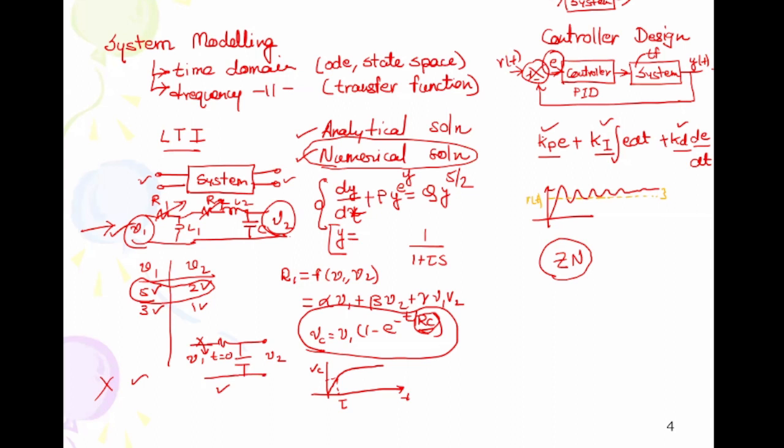Now you have to apply optimization. When you apply optimization, first of all, somewhere you have to write what your objective is and what you basically want to come out with by using optimization. What is your aim? There is a very small difference between objective and aim here. Dictionary meaning both are the same, but here there is a small difference. My aim is to find Kp, Ki, and Kd. This is what you want. This would be the solution to your problem.